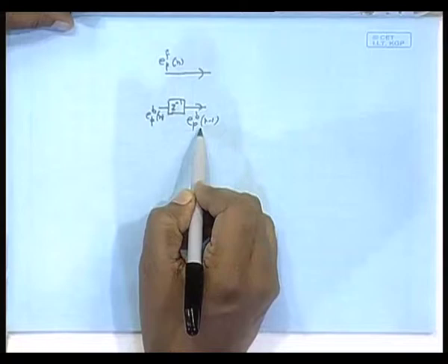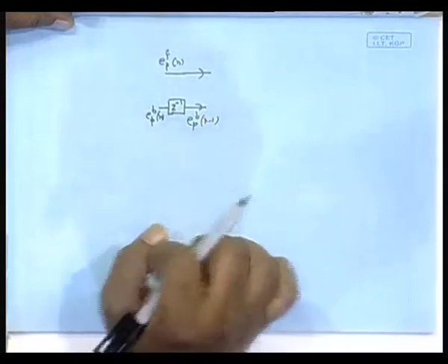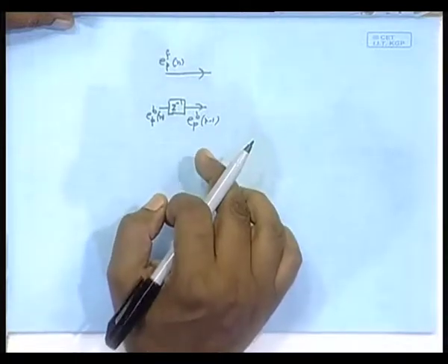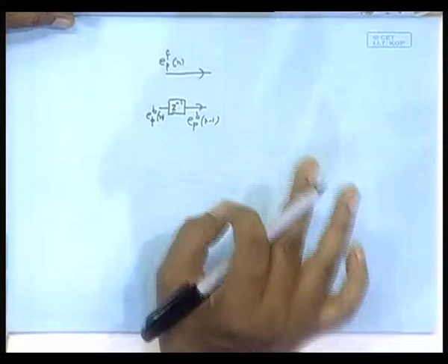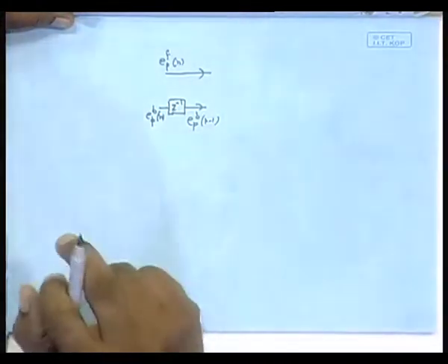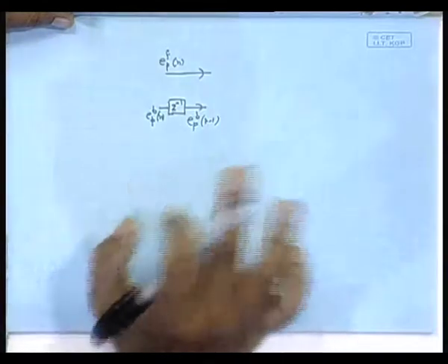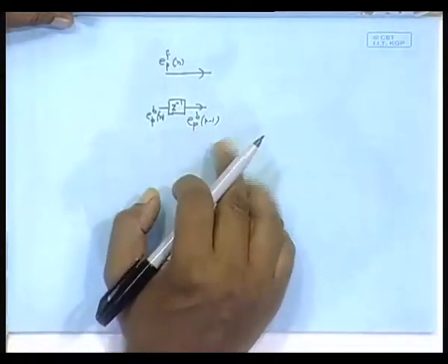Here it is not the last but one component of that vector. That vector itself is different because I am taking data up to n minus 1th index. Then I do least square minimization and get a new set of combiner coefficients. By them, if I combine the columns of the data matrix, I get a new orthogonal projection. Then take the error, the last component of that error vector.